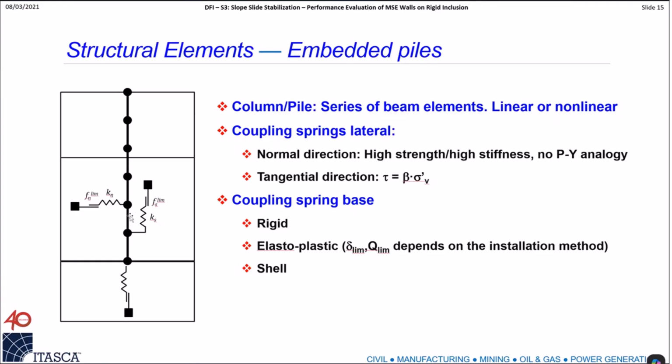It should not be done. The way I do it is actually the opposite. Since the soil is present with its constitutive model, the deformability, the shear strength, and whatnot, these springs only need to be seen as a contact element. They transfer the forces. That's it. In fact, they need to be significantly stiffer than the soil itself, exactly for the reason that I was mentioning for the series, because 1 over K is 1 over K spring plus 1 over K soil, right? So this 1 over K spring needs to be small so that the sum of the inverses is essentially equal to the stiffness of the soil, okay? I hope that this is clear.